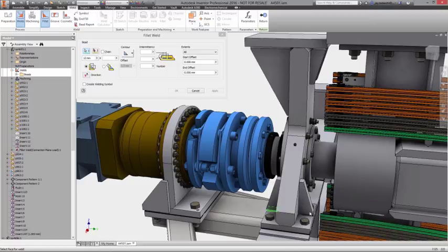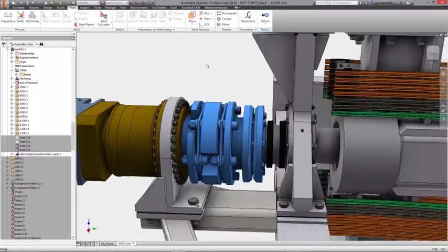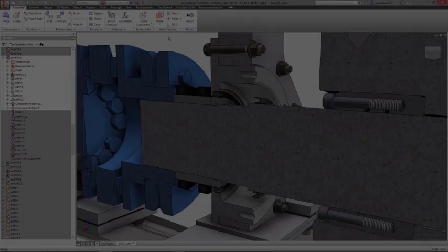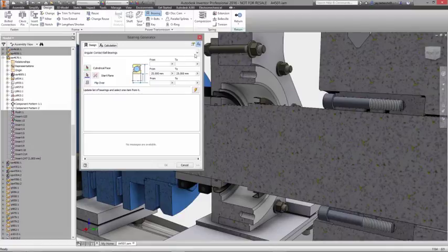This is made easier by interacting with the model to specify the parameters of the joint, such as measuring an edge for the length of a weld, with the calculator raising red flags if the yield strength will be reached, while also providing guidance for modifying the input parameters to produce an acceptable design.